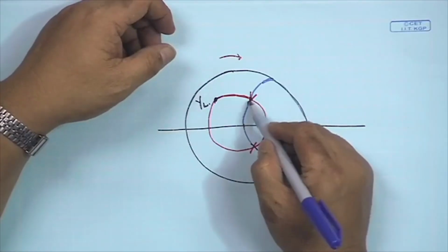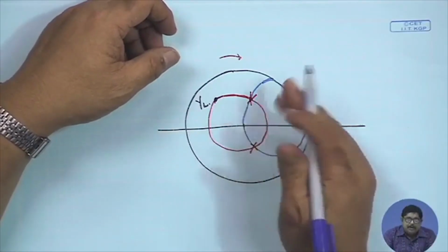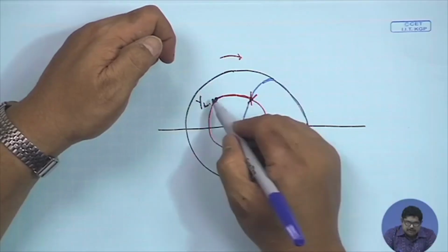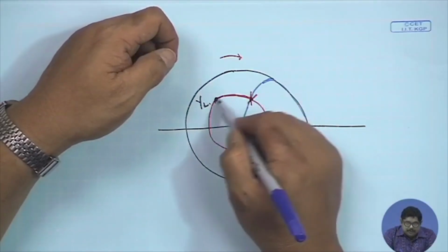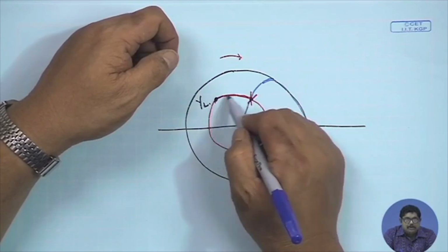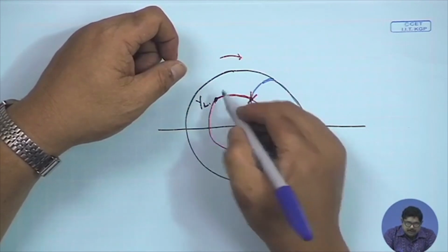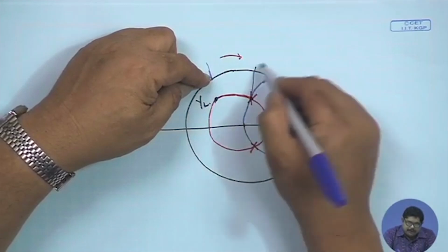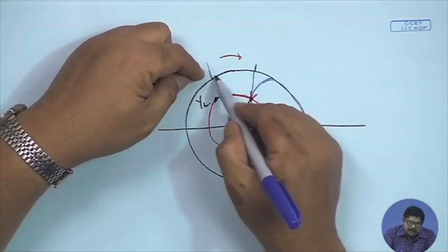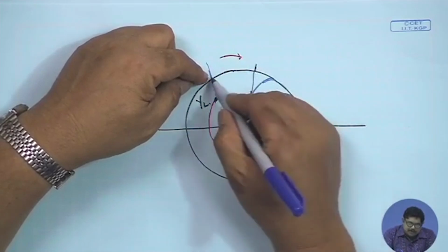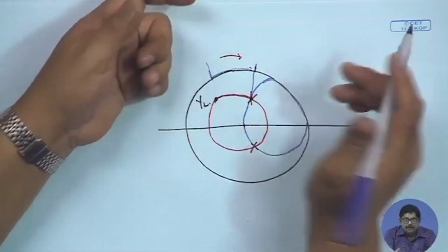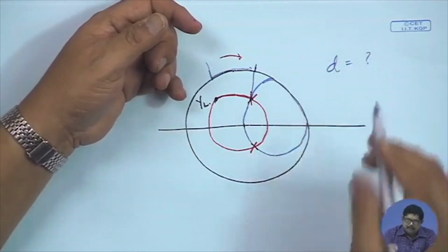Now, after coming here, what happens? That means, this part is given by the D portion of the transmission line, that transmission line portion between the load and the stub, that changes this. So, the change in the transmission line, how much transmission line length, that you will read from here, because this one has a chart in the lambda scale. So, from that you can find out what is the distance you have travelled, and from that you can find out what D is, how many lambda.